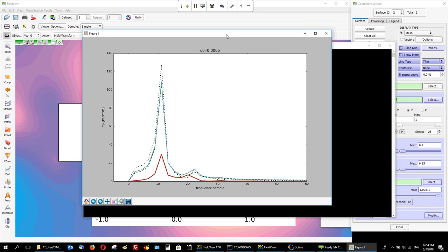So it's a pretty standard plot. I'm guessing that most people on the call are familiar with that kind of thing. We are looking at the magnitude of coefficient of pressure variations in the frequency domain. I just want to mention that this one has been computed after the time average has been subtracted. So that's why we're going down to 0 here for the first frequency bin.